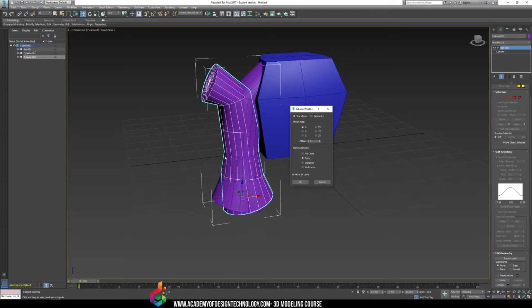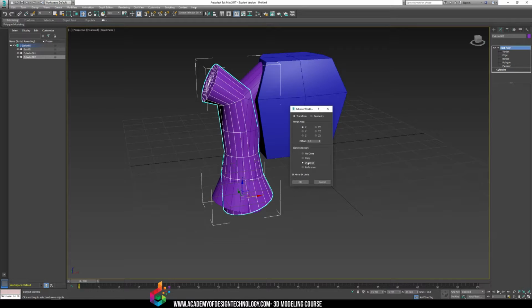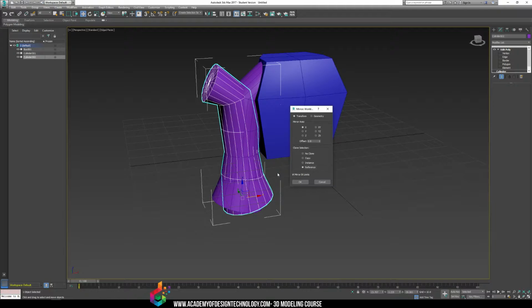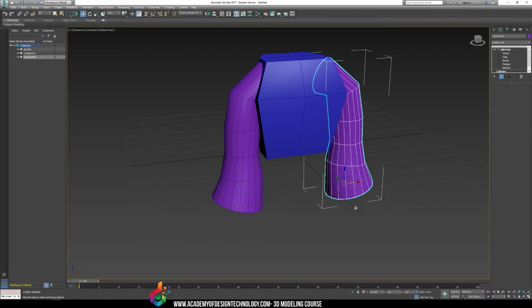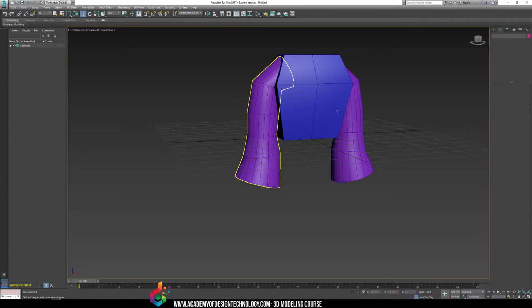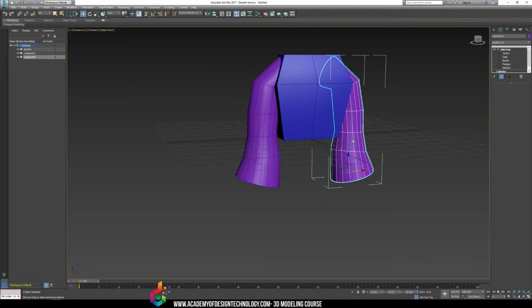If you're working on an object, like an arm here, and you're going to copy it, if you're still working on it and will modify that mesh still, I would suggest to copy it as a reference or an instance. An instance is a single object that will reflect what the first object is, and the reference is the same thing, except we can actually have multiple of these. I'm going to create a reference. I'm going to click OK, and once I put it into place here, yeah, that's a pretty correct position right there.